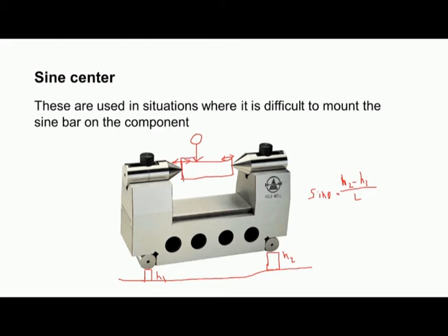So, we should place the tapered component here between centers, and then we should adjust this height difference, H2 minus H1, till the dial indicator reads 0.